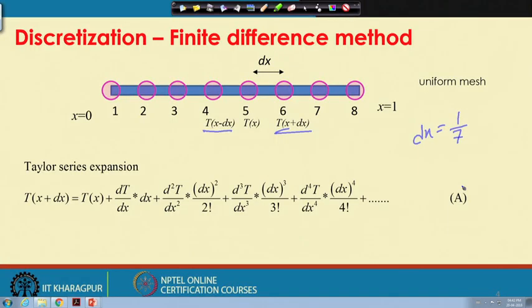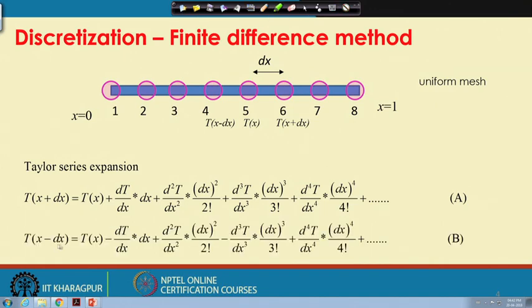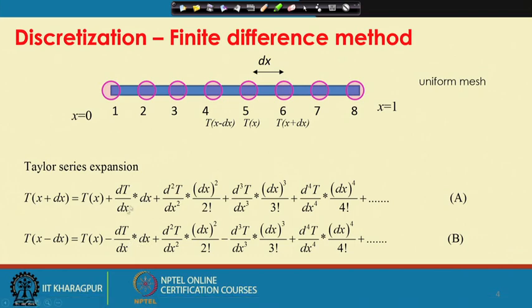However, we are not discarding it at this stage. What you see, we can similarly do a Taylor series expansion for the next term, which is T(x-dx), is T(x) minus dT/dx dx, only because dx is negative here. So, only the odd power terms will have a negative coefficient.